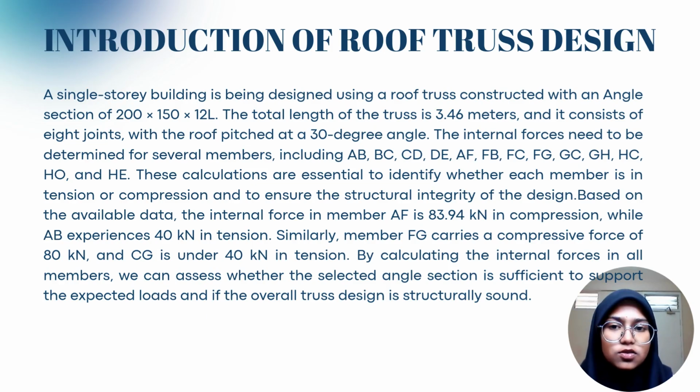The internal force needs to be determined for several members, including AB, BC, CD, DE, AF, FB, FC, FG, GC, GH, HC, HO, and HE. These calculations are essential to identify whether each member is in tension or compression, and to ensure the structural integrity of the design. Based on the data available, the internal force in member AF is 83.94 kN in compression, while